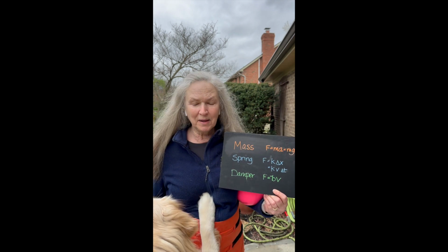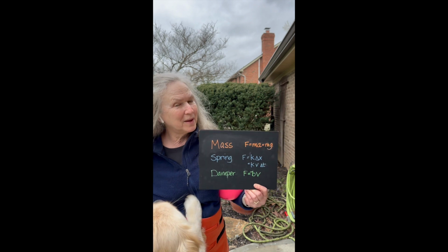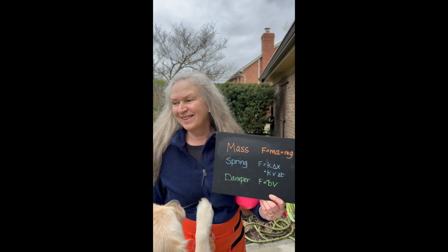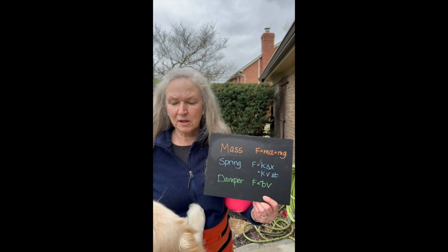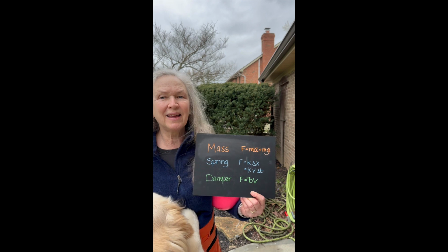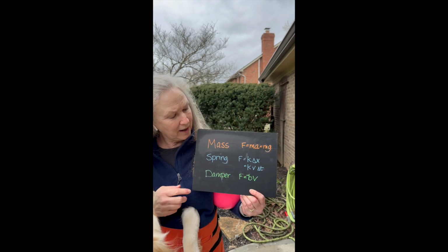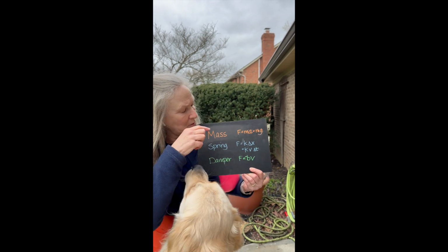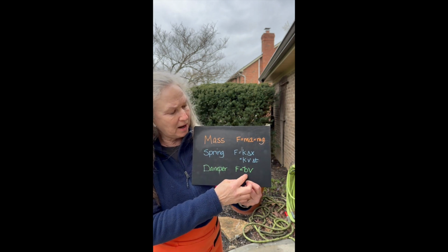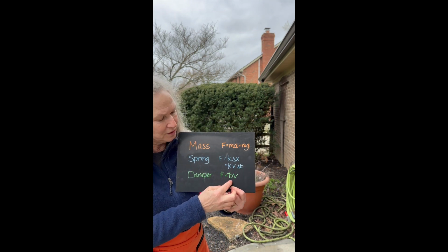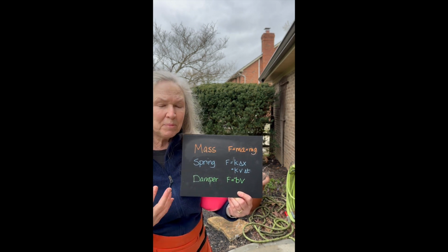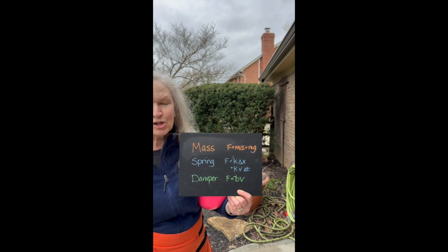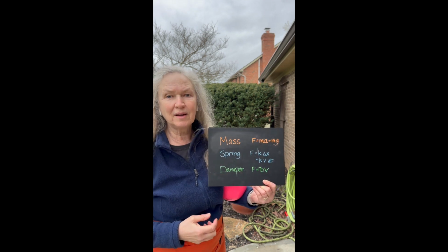My third element is a damper, and that's analogous to a resistor in an electrical system. So you know what resistors do? Well, a damper would be like a dash pot in a water system. Dampers dissipate energy, hence damper. And the force on a damping system is equal to minus the damping coefficient, minus b, times the velocity of the element. So the damping force always acts in opposition to the velocity of the object.